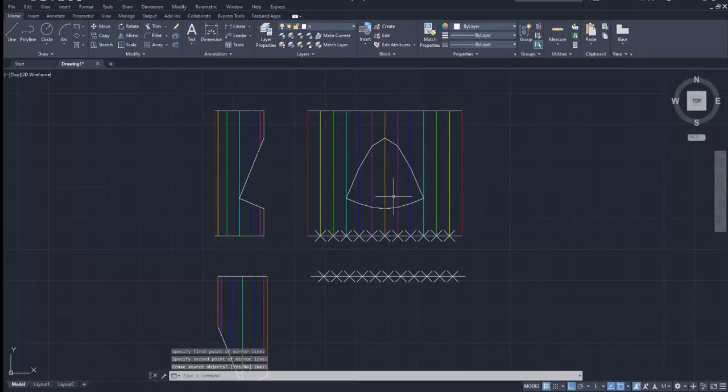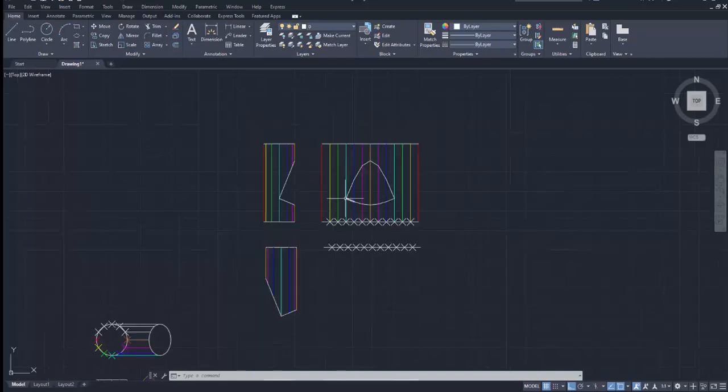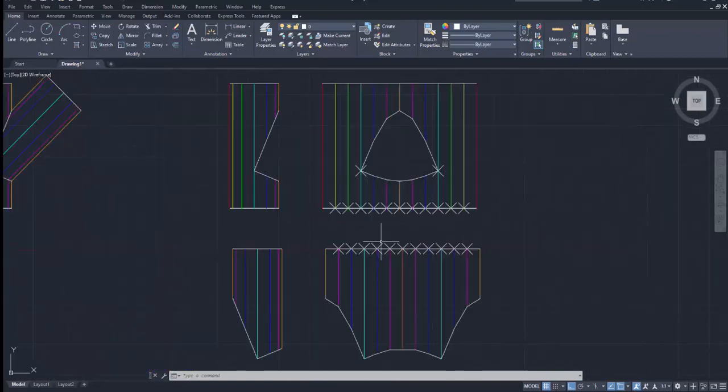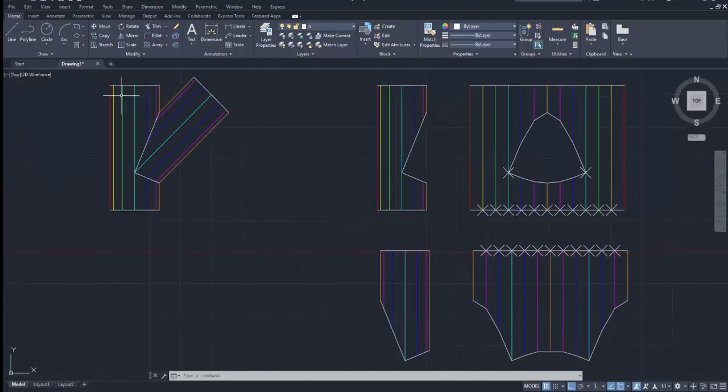And of course, if you were on paper, you could lay this out, put your spaces, draw your vertical lines, and then take a compass or a divider and measure this distance. Transfer it here and draw your line. Measure this distance. Transfer it over here, draw your line, so on and so forth. Same deal with the bottom one. Transfer our distances over, gain these results, and this would be your development of this 4-inch 45-degree tubular round intersection.